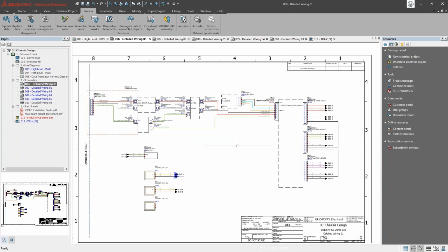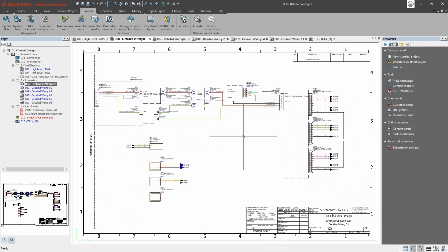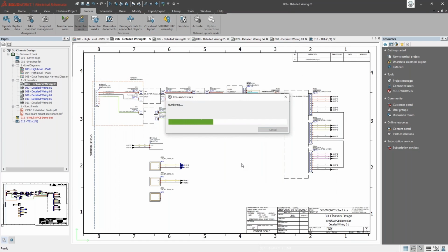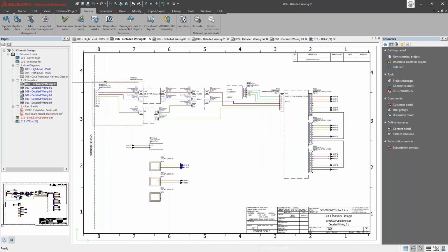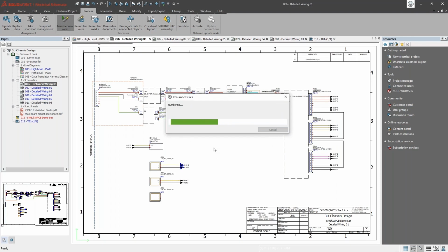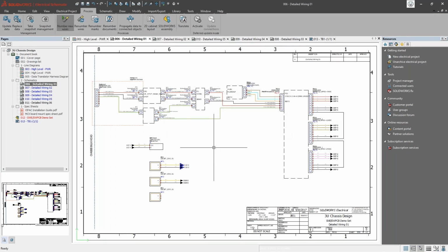So once you have your numbering scheme set up and you route everything, if you ever need to change anything, well, oh, the mechanical engineers came in and said they need to move 47 things on you, so you might as well just renumber everything. Well, I just deleted it. I can go ahead, renumber. I'll take a sip of water real quick. And just like that, my project is renumbered from top to bottom, left to right.